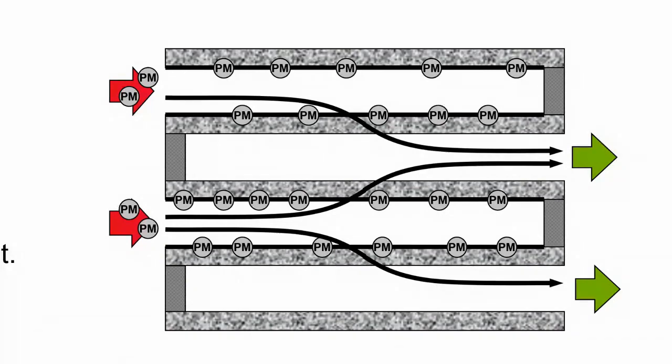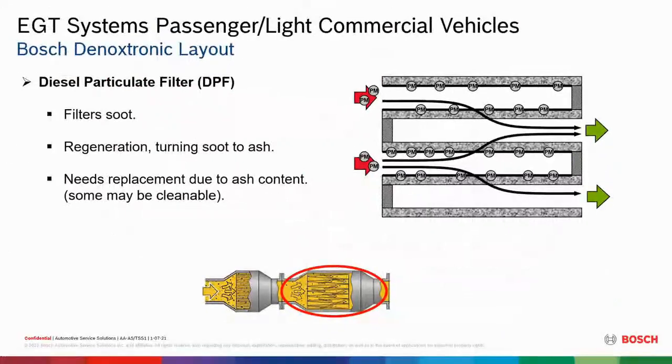A scan tool will be put on it, and 30, 45 minutes later, after high RPM and a vast amount of noise from cooling fans and everything running at high RPMs and exhaust flowing out that tailpipe, it will burn that particulate matter off and turn it into soot. But again, the soot load does matter. We've got to keep an eye on that as well.